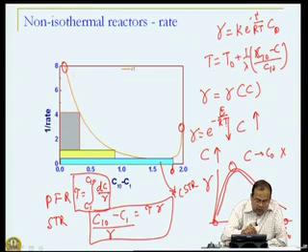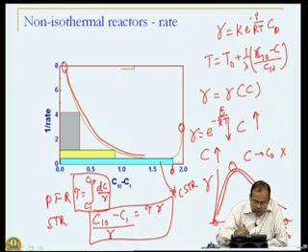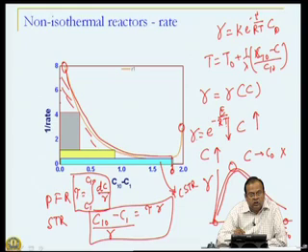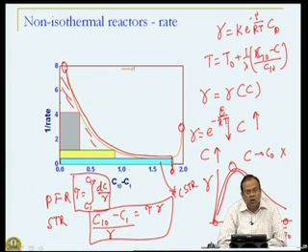It will be the area under this 1 over R versus C10 minus C1 curve. So, this entire area, which certainly is much greater than that for a stirred tank reactor. Or in other words, for a non-isothermal reactor, adiabatic reactor, the residence time required in a stirred tank reactor to achieve certain conversion is much smaller than the residence time required in a plug flow reactor. So, this is different from isothermal reactor.